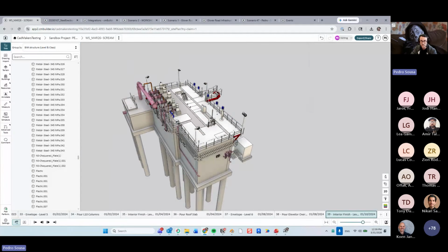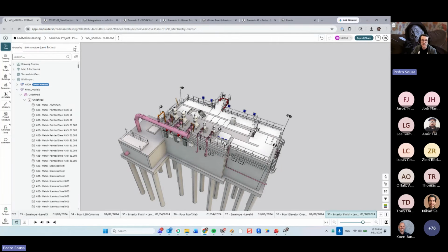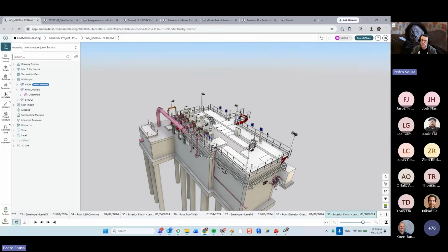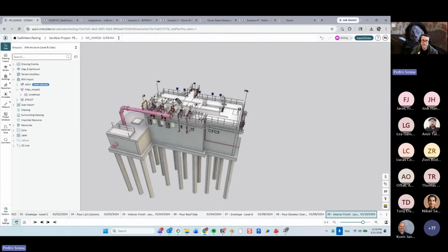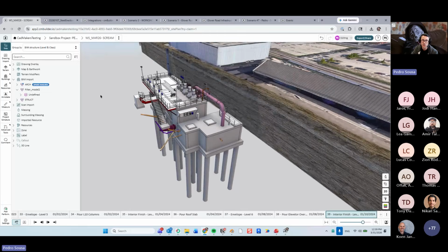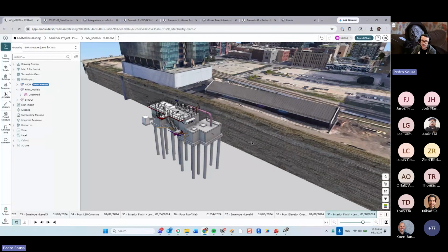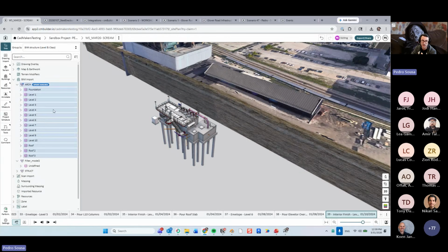Okay. So basically the idea here is that learning how to work with your tree structure and these selection methods will make your life easier because you can select a bunch of parts that fit a specific criteria and remove them all at once. But the thing is, when you work with Navisworks models like NWD and NWC, plus FBX models, your tree structure is different than working with IFC and Revit files.